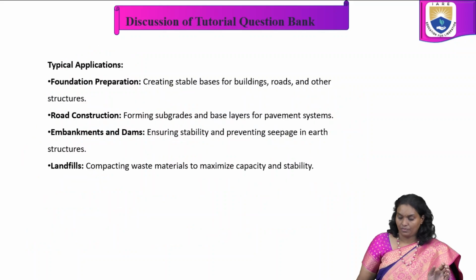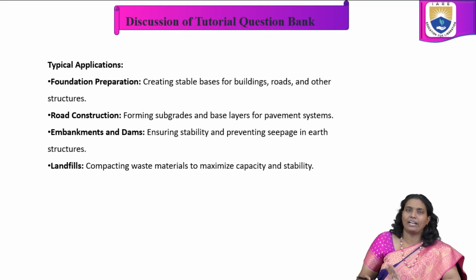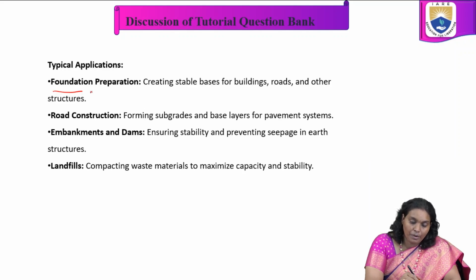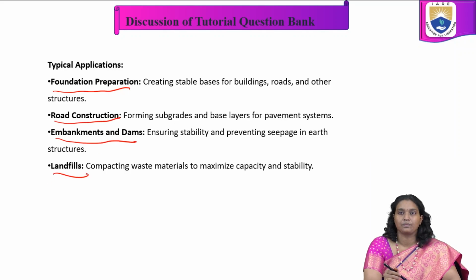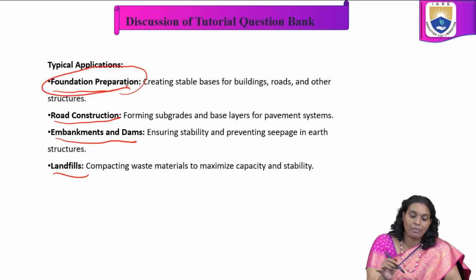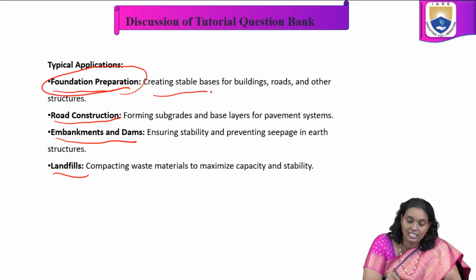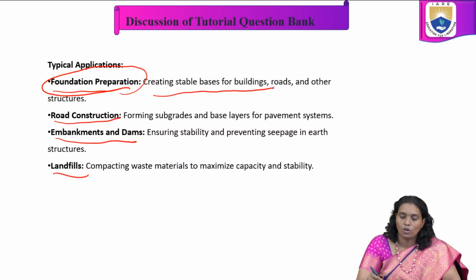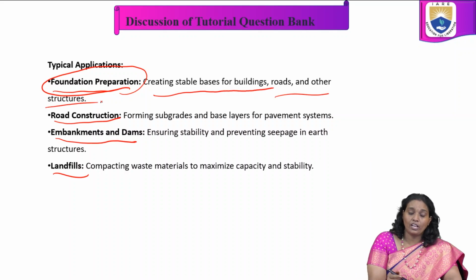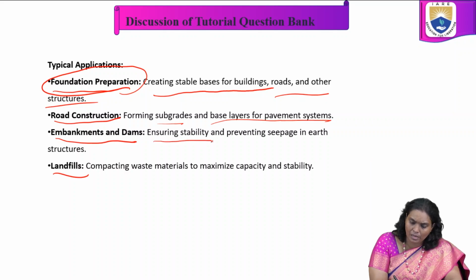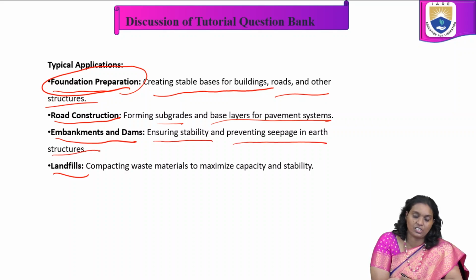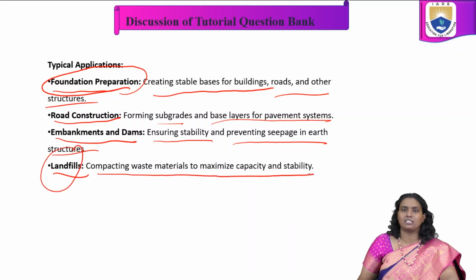Now, the applications where we are going to apply it are typically foundation preparation, road construction, embankments and dams, and landfills. For foundations, what kind of application is it? It stabilizes, creating a stable base for buildings, roads and other structures. In road construction, forming subgrades and base layers for pavement systems. In embankments and dams, ensuring stability and preventing seepage in earth structures. In landfills, compacting waste materials to maximize capacity and stability.